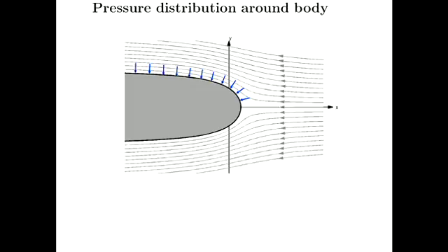So what we wanted, we know the velocity field, we know the flow field around this geometry, this half-Rankine body, which we could use to model a nose cone. And what we'd want to know is the pressure distribution acting on the surface of that body, because that's going to tell us the wind loading on that body. It's going to tell us, for example, how much thrust we need in order to keep that body moving along. So the question is, can we just apply Bernoulli's equation? And the answer to that is, not to give too much away, yes, we can.